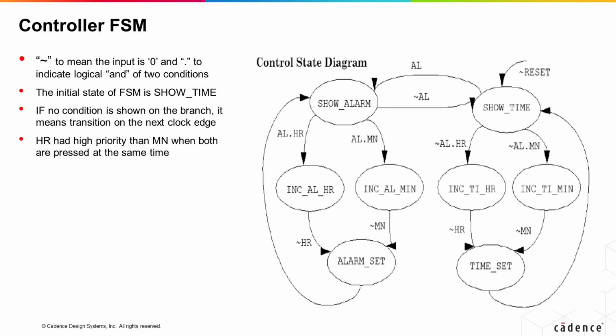Also, if in increment_TI_min state and MN goes 0, the transition occurs to time_set state, and the transition occurs to show_time in the next clock edge unconditionally.